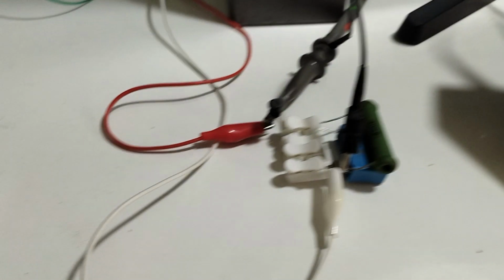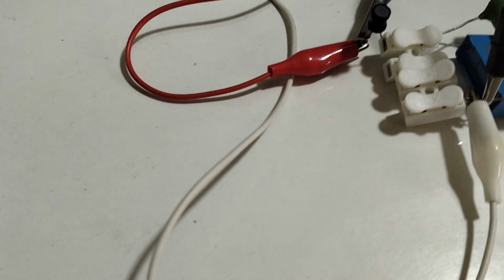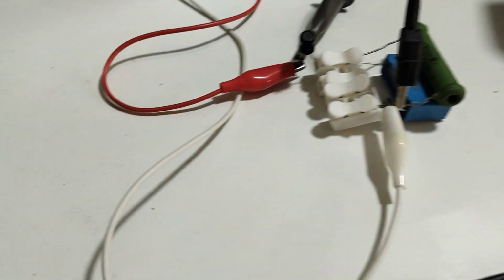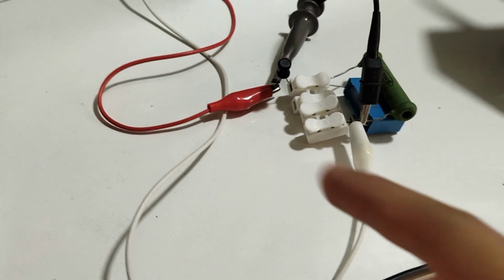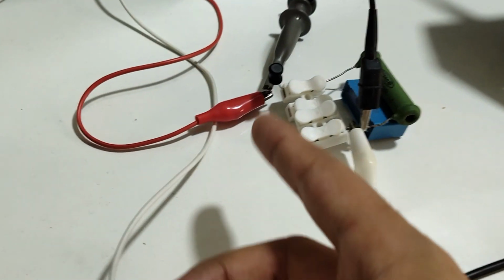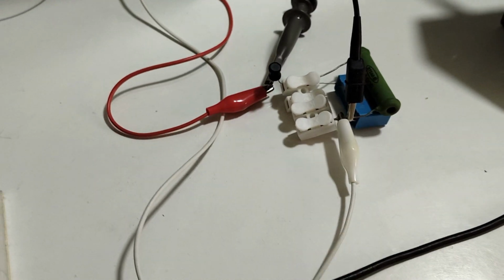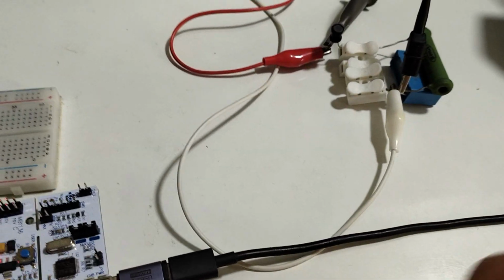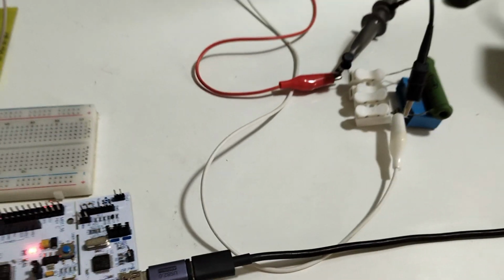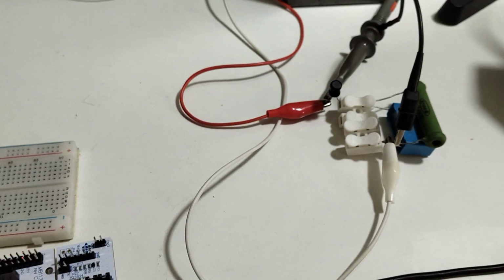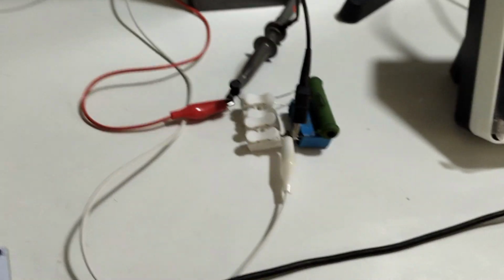So our output should look like a pretty good sine, and it should attenuate the switching and retain the 50 hertz fundamental. It's a low pass filter. And since it has two energy storage components, the inductor and capacitor, it's a second order filter, so it has a slope of minus 40 decibel per decade. If you want to know more about that, you can see the filters video which I've done before.